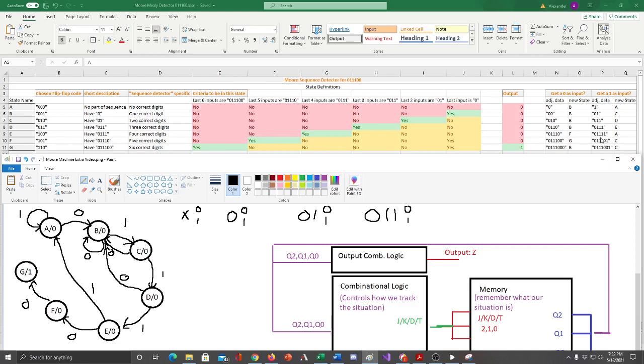There's a couple of mismatches there. 1, 0, 1 does not meet this, but there is a 0, 1. And so as we do pass this check, we run it all the way back, that's C. So we get to C by getting a 0, then a 1, which in that situation where we're in F and get a 1, the 0 got us into F, and the 1 would take us back around to C.